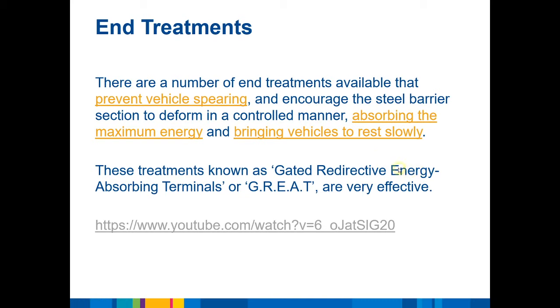You really want to see the benefit of those things in absorbing energy when the vehicles strike the end treatment, and that steel is made to deform in that way. It's taking energy away from anywhere that it can do any harm. It's not storing it in a spring or raising it up in height, in gravitational potential energy. That energy is being used up in deforming the steel. So yeah, they're very, very safe things.